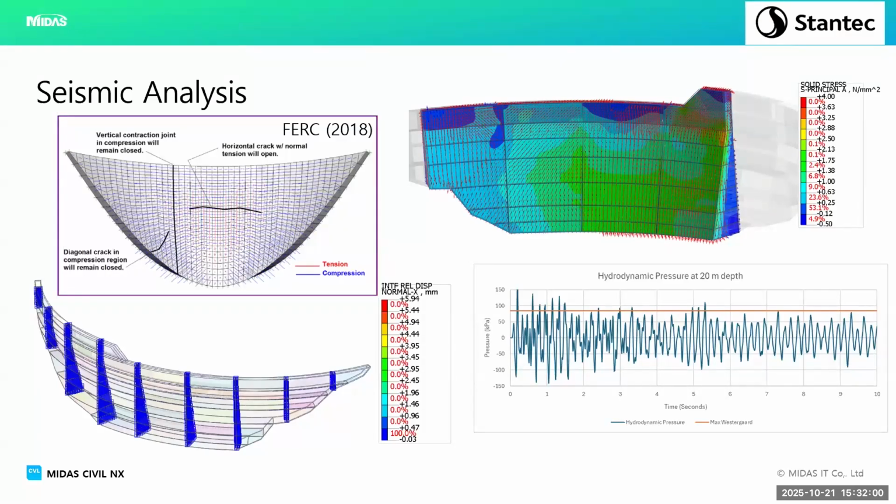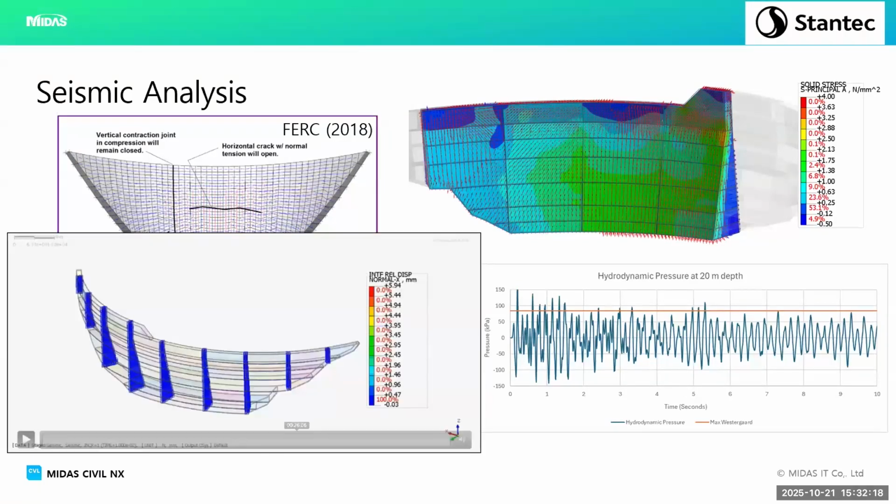I don't expect it to be exact because Vestergaard's formulation was based on a rigid dam. Arch dams are extremely flexible, so you can't get the same, but it does give you some form of confidence in what you're getting. Here's my little videos.